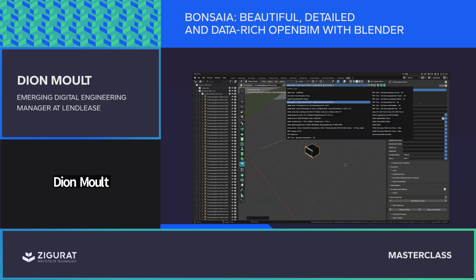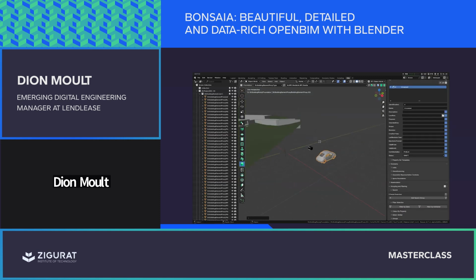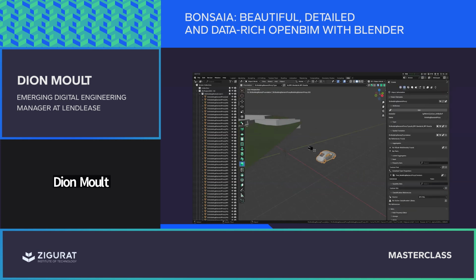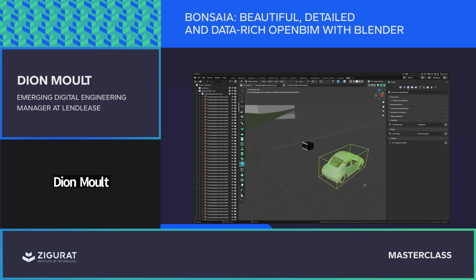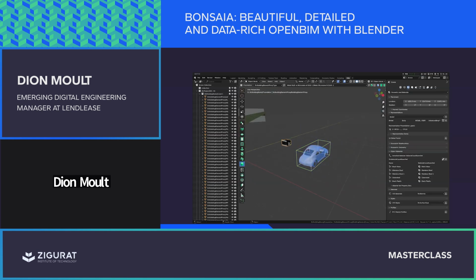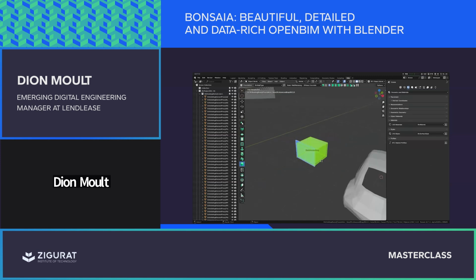I can add in, I guess, this car. And this will tell me in a great level of detail, you can see here, I'm editing the IFC. I'm adding new objects. And each one of these objects is a completely new IFC element with its own properties, its own quantities. It can have its own geometry and relationships. So for example, I can dig into this and see that this car is modeled using a connected face set geometry, whereas this microwave is modeled using advanced B-reps.